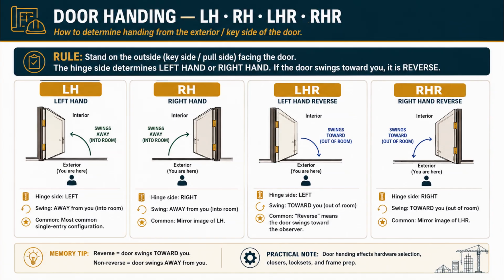That's the whole method. Left hand, LH. You're standing on the exterior. The hinges are on the left. The door swings away from you, into the room. That's a left-hand door, and it's the most common single-entry configuration you'll encounter.